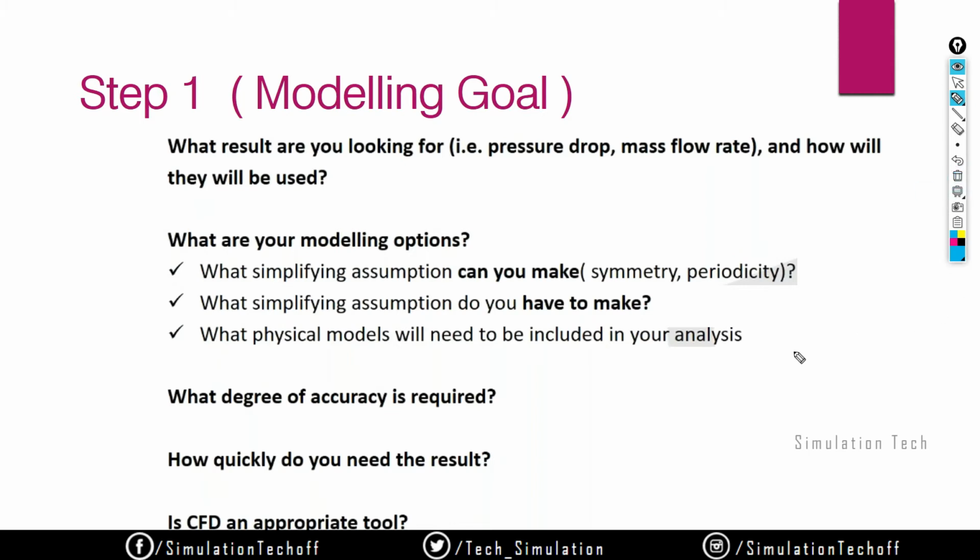You don't need to design the entire model of the component. Okay, so CFD is used in all the stages. Right, if you want to design a car, obviously you need to do an aerodynamic analysis, right? For that you don't need to model the entire thing inside the car. Only the aerodynamic analysis will take place on the outer surfaces of the car. So you just create the outer surfaces of the car and do the analysis, right? So that is what they meant by the physical models you need to include in your analysis.